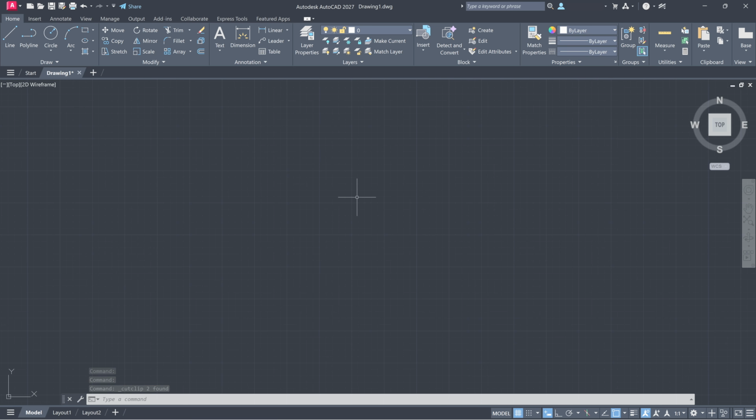Sometimes beginners get confused because the arc curves in a different direction than they expected. That usually happens because of where the points are selected. The start point, the second point, and the end point control the arc shape and direction. So if the arc does not look right, don't worry. Press Escape, start the command again, and pick the points in a better position. With a little practice, you'll understand how the arc follows the points you selected.